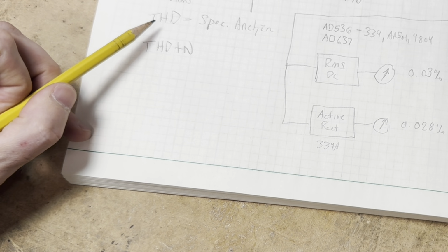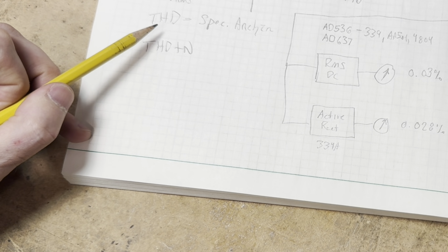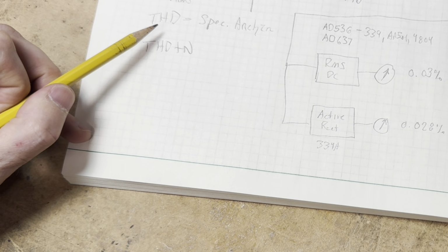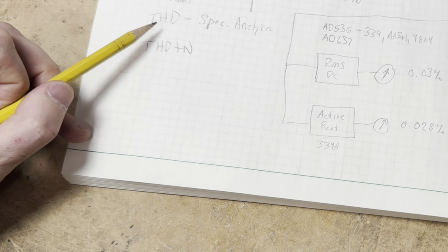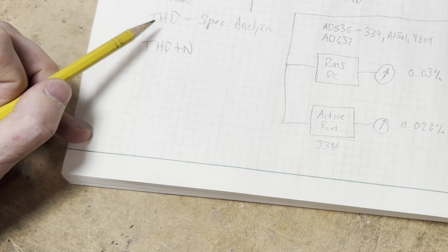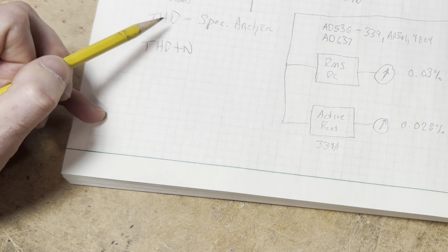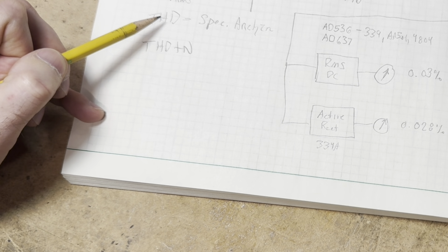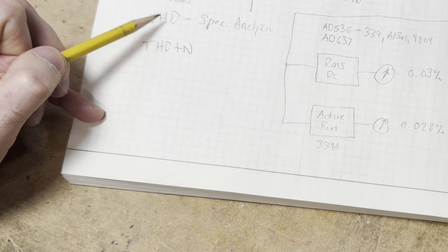where we might look at a signal on a spectrum analyzer and we might see the levels of our harmonics. We look at a 1 kilohertz signal on a spectrum analyzer and we would see our 1 kilohertz signal level is normalized to some 0 dB value. And then we would look at our second harmonic content, which may be at a level of minus 60 dB below our fundamental.